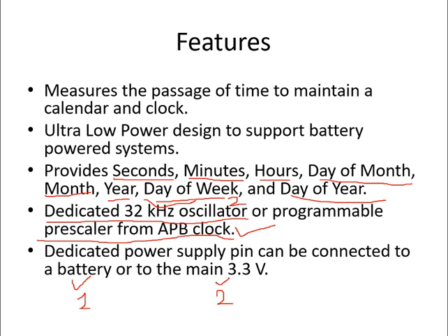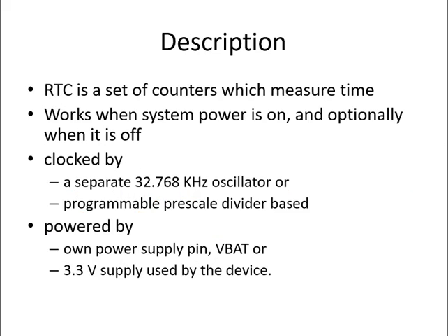Now, what is the need of a separate oscillator and separate battery? Because once you program the RTC, it can work independent of the LPC 2148. Even though you switch off the power supply for the LPC 2148, the RTC will continue to work, and therefore you have the option of a dedicated oscillator and dedicated power supply for the RTC.